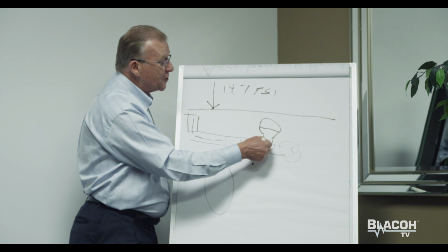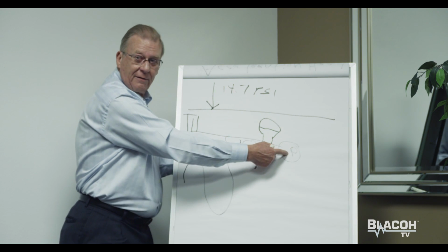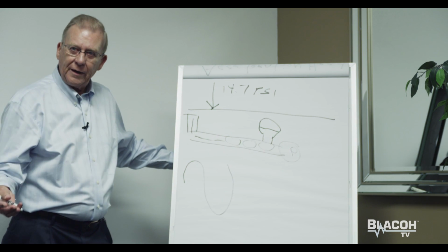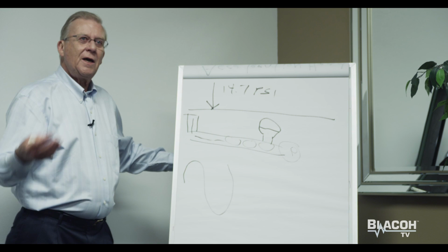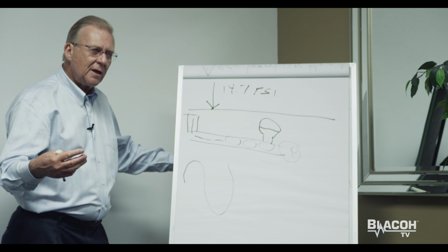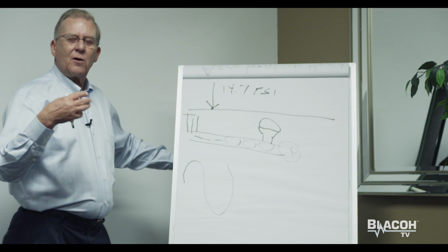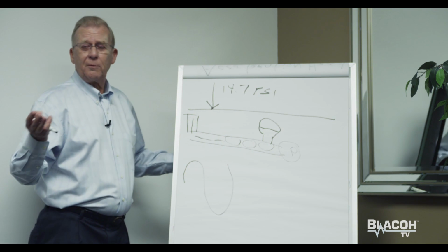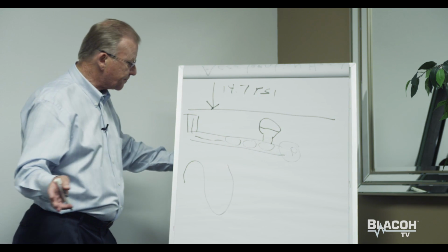So the pump then, when it shifts, pulls this liquid out of here. It's not having to re-accelerate the whole line. It takes less energy, ensures that there's no cavitation, ensures that we get full fill in each of the chambers, and it's particularly important on multiple piston or multiple diaphragm pumps.